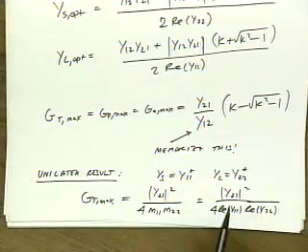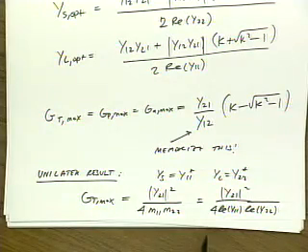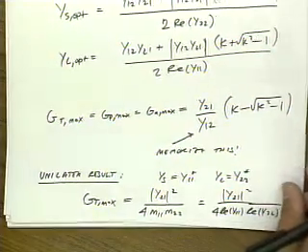So that long calculation we did to get the power gain of a MOSFET, we could just directly plug into this equation. y21 is gm, the real part of y22 is just RO, and the real part of y11 is basically just a series to parallel transformation. Okay. Questions or comments? Okay,